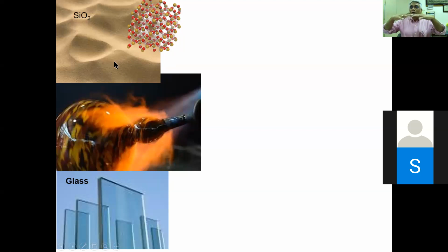Because see, the molten state is a good platform for atoms to start moving towards their lattice positions like this. But then you need to give time for that. You need to give a lot of time for that. If you give a lot of time for this molten solid to settle down into a regular periodic atomic arrangement, right? Then you form a single crystal. So that's a tedious process, to get a silicon dioxide crystal or any other crystal from the melt. So I said for thin film growth, for PVD technique, you need a solid or a molten source. But for single crystal growth, molten sources are a must. You must start from the melt. Otherwise, there is no crystal growth.